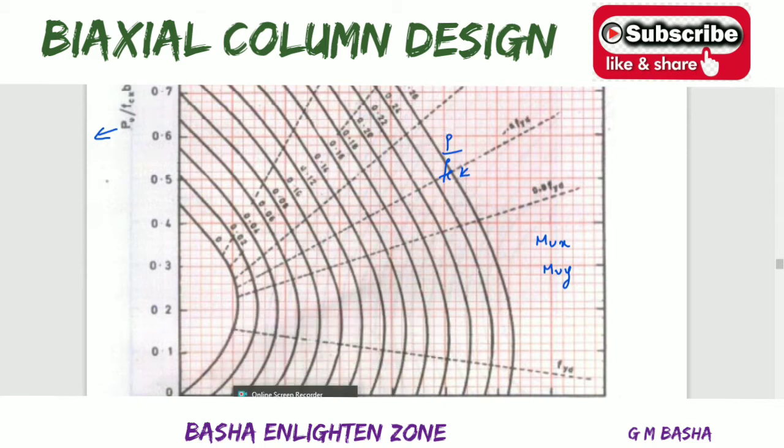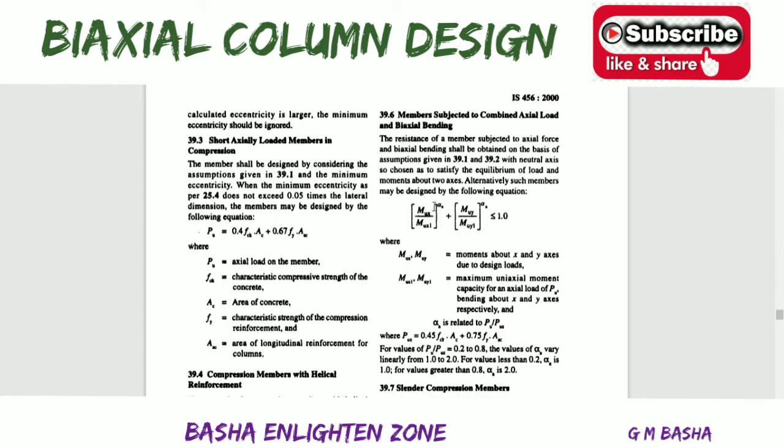And before going to that one, please see the formula in IS 456, which was given in clause 39.6, that is members subjected to combined axial load and biaxial bending. So that is (Mux by Mux1) to the power of alpha n plus (Muy by Muy1) to the power of alpha n less than or equal to 1. Please take down this formula first and then see here: Mux and Muy are the moments along x and y axis, where Mux1 and Muy1 are the uniaxial moment capacity for an axial load of Pu bending about x and y axis respectively.